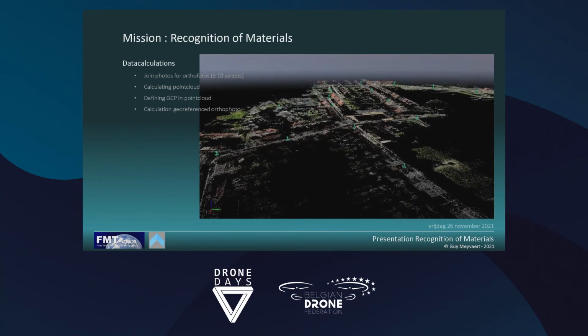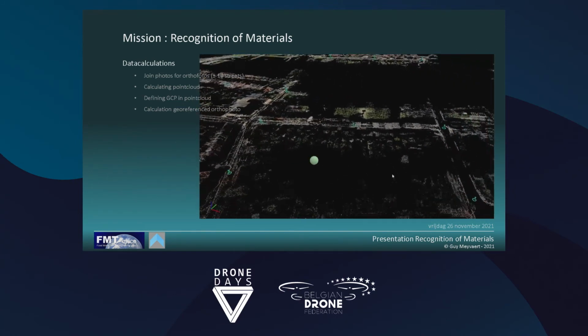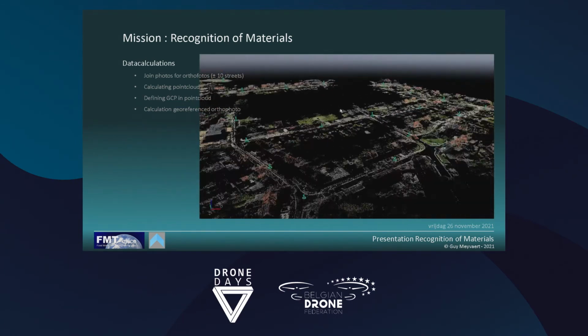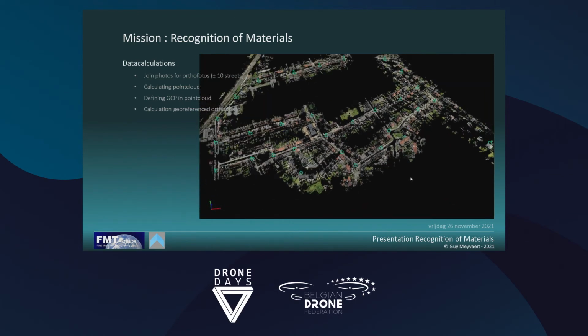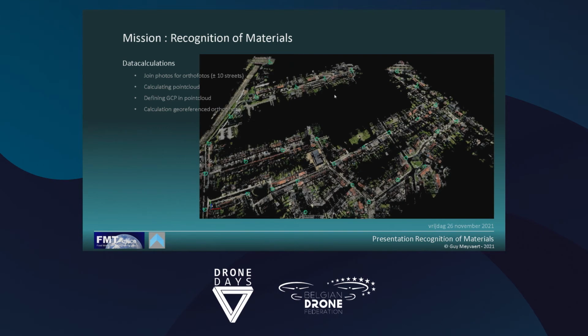We are trying to get an accuracy of about 1 centimeter. For our client, it's not that important, but for the recognition of the material, it's necessary that we have that detail of 1 centimeter. So here you saw the first point cloud and the checkpoints, the ground points that we have placed. And afterwards, we are going to calculate the right orthophotos.